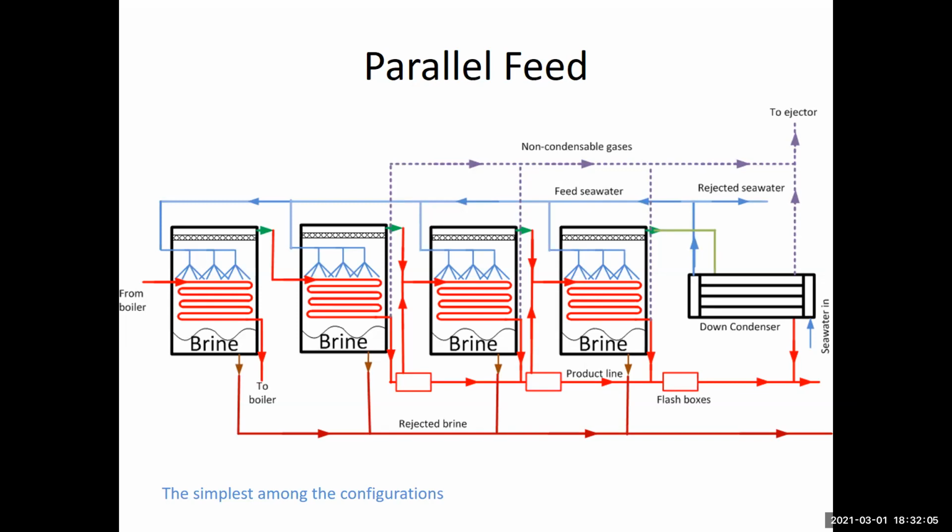Would that mean that in every one of these effects, there has to be sensible heating? Note that for each effect, the saturation temperature is greater than TF. So heating from TF to the saturation temperature is step number 1. Then sensible heating, then latent heating of evaporation is going to occur.